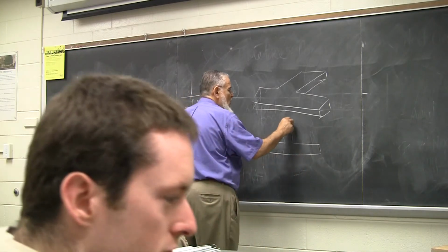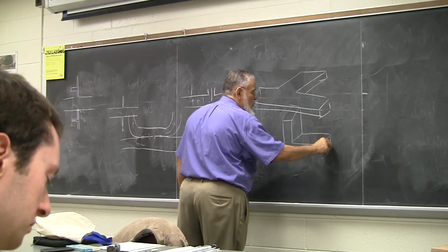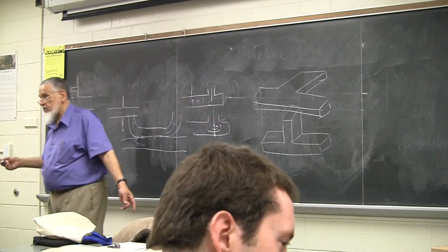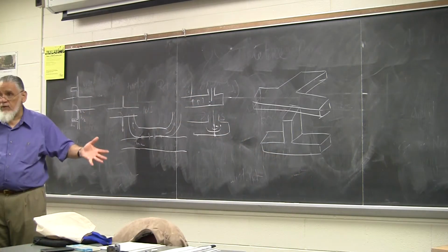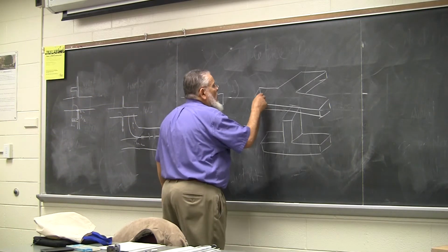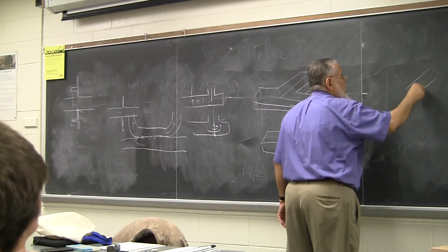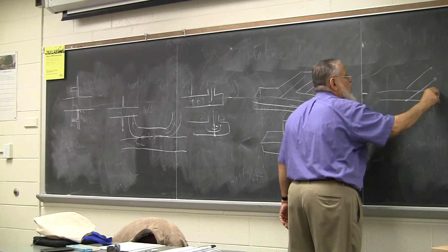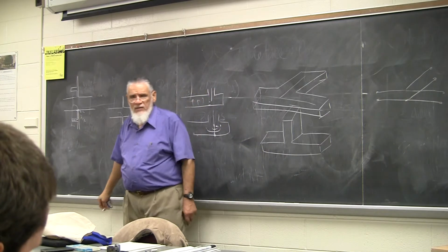So if we have those in a system, and we'd like to analyze the system, what do we do? All right? What we do is resort to the S parameters. We develop the scattering parameters of these devices and use them instead of working out the field equations. Okay? So basically, you would think that you have a line here, another line going there, so you can just approximate that to two transmission lines like this. So it would be like the stub problem that you worked on before. Okay? That's an approximation. That's not really an exact thing.